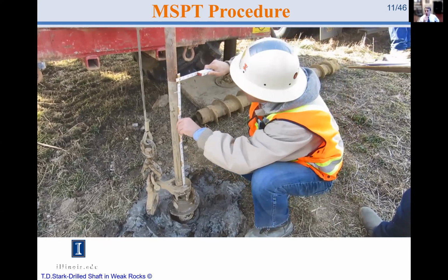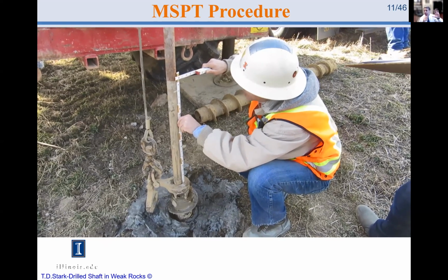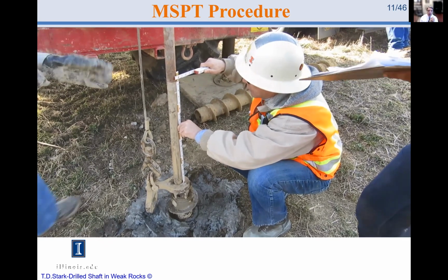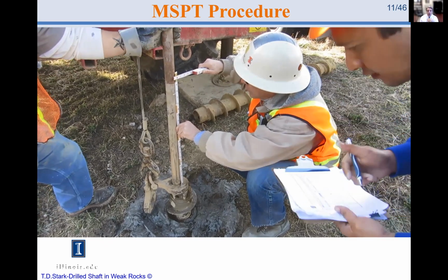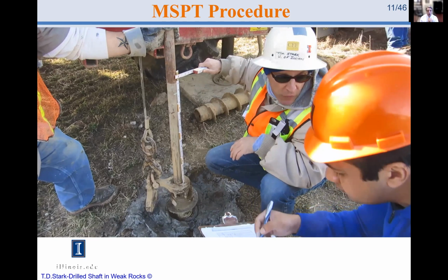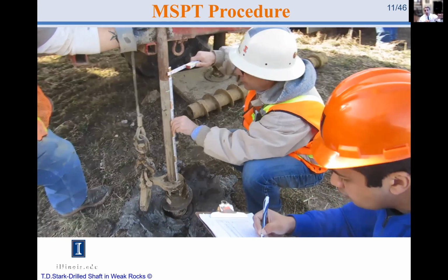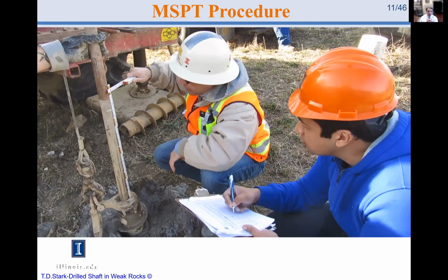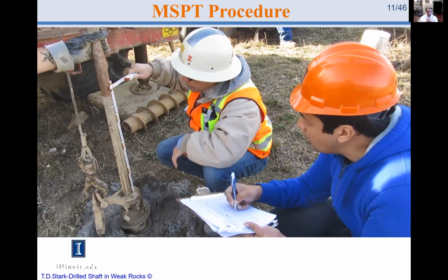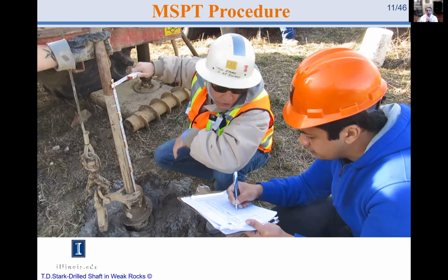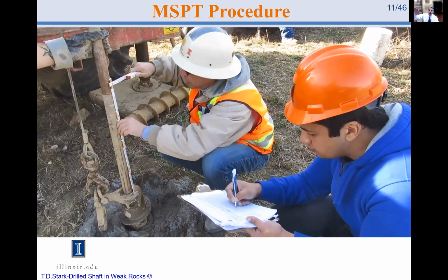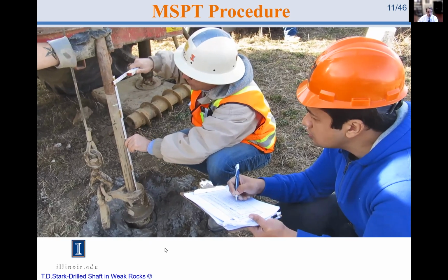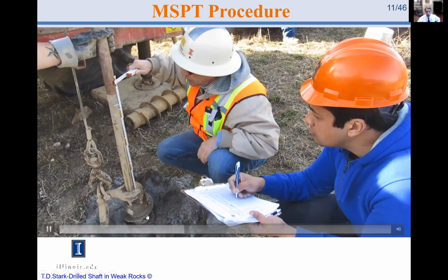So we measure the amount of penetration at every 10 blows. So if we were going to go to 100, we'd have 10 of these. But you'll see in just a minute, when you're on virgin material, it doesn't move much. And so you really only need a couple points now. Notice the mark's not moving much at all now. And so it's pretty constant. Now we know we're in the linear portion, but this video goes out to 100. I won't run it to 100.